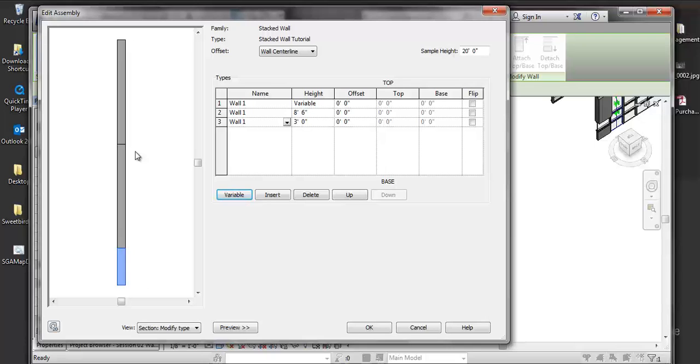I mean, this is just a kind of easy way to go about it. If I know I'm going to be making this wall 40 foot in the air, and I know it's continuous around this whole box, I'm going to take the time to make it one wall that handles that whole condition. If you guys go crazy with a lot of patterning and everything else, maybe in that case you're just doing separate walls and leaving it that way. It's really just a matter of what you want to get out of it.